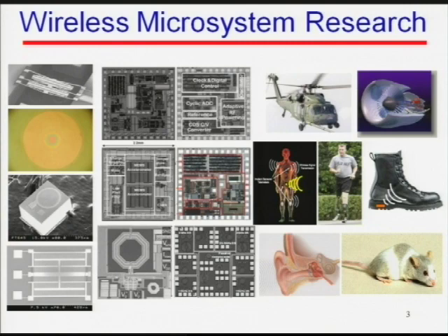This is the silicon-based pressure sensor, and this is a silicon-based accelerometer inertial sensor that we designed and fabricated using an external foundry. So all these devices are designed for specific applications. For example, the strain gauge sensor is used for sensing the surface strain profile on a rotating element such as helicopter blades, so that we get a better idea of the fatigue of a rotating element, know how to monitor the health condition of the mechanical elements, and be able to replace some of them before they break down.